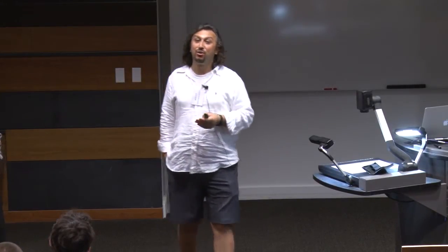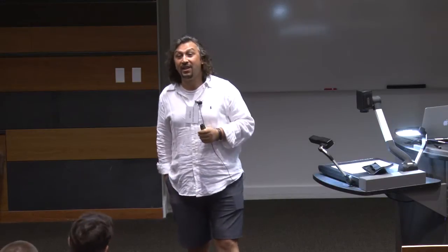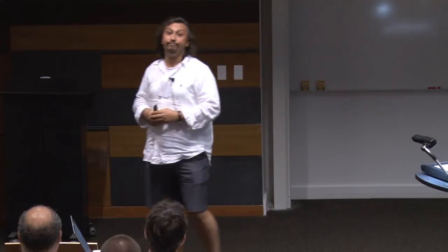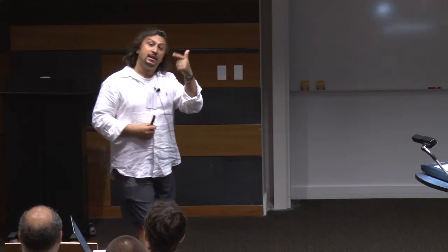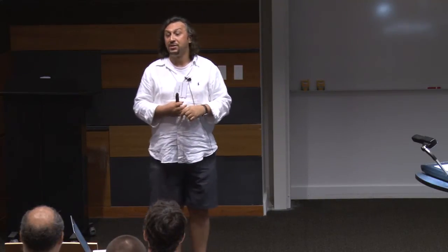If you look at the lizards running on sand, they have similar trajectory and leg dynamics, interestingly. However, we haven't done enough analysis to give you an exact answer about that. I think the tougher one for us is ground, because that drastically changes the reaction forces, which become so huge. But you guys have solved, not solved, but let's say, are solving the ground problem. And the problem will be this: the same legs must handle very high ground forces, medium sand forces, and very low water forces. How can you have a system that can handle all of them? From the mechanical design, in the sense of compliance, leg trajectory and gait, and then control-wise, active stiffness control or passive stiffness control, because with one stiffness, I don't believe we can handle all of the surfaces.